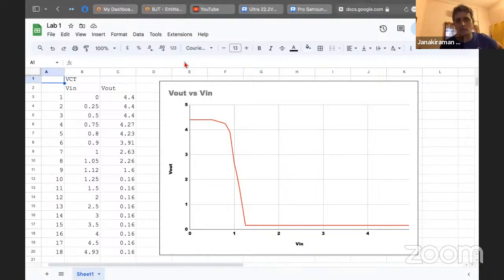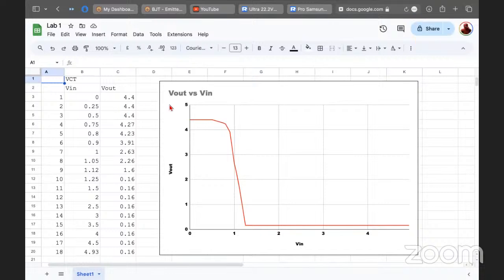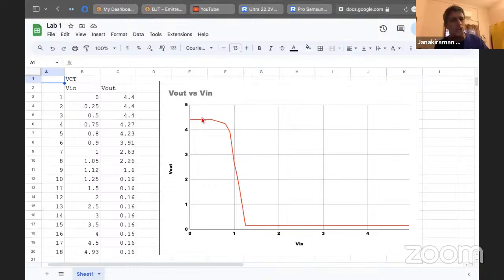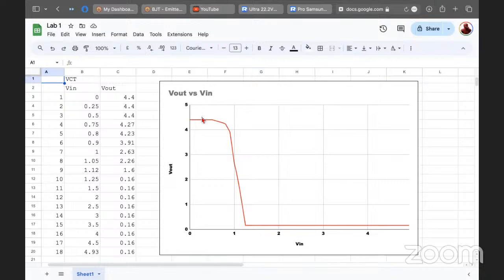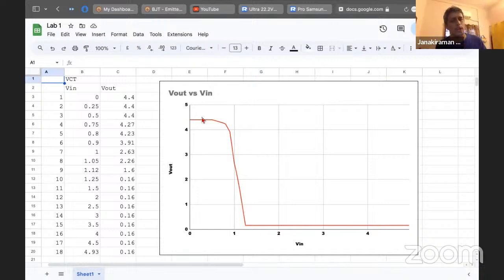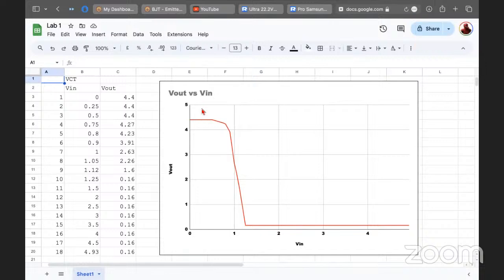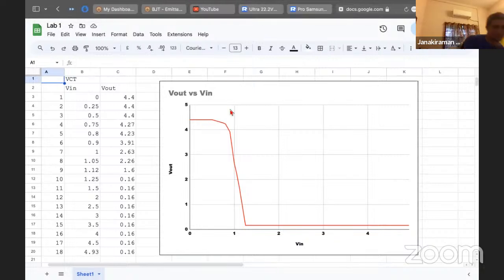But is this V out versus V in or Y versus A? Sir, I considered V out to be pin 3 and V in to be pin 2, and I explained that in my video. But this is just the output of one NAND gate, no? I am asking you, if I do the same experiment with two NAND gates, how will the VTC look? Yes, sir, I'm just drawing that. I'll just take a second. Okay, fine, do that.